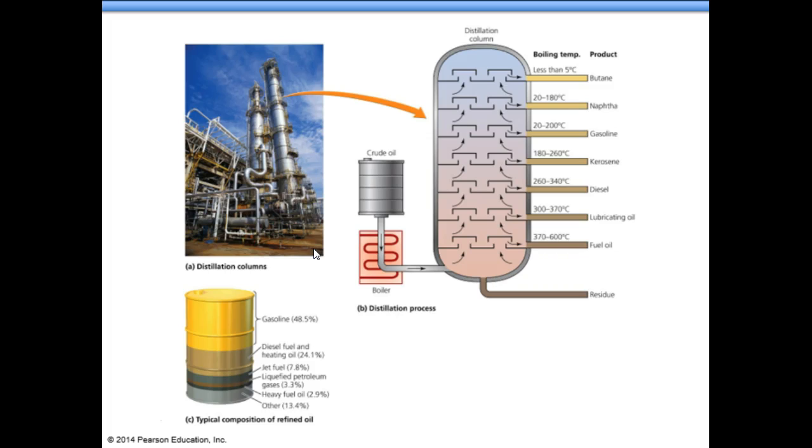Okay, then in B, they'll enter this distillation column that you see here, and the constituents that boil at the hottest temperatures and condense readily once the temperatures cool will condense at low levels in the column. Constituents that volatilize at cooler temperatures will continue to rise through the column, so they'll work their way up through the column at higher levels where the temperatures are cooler. This is where we get our heavy oils from.